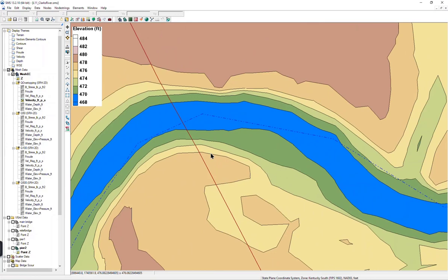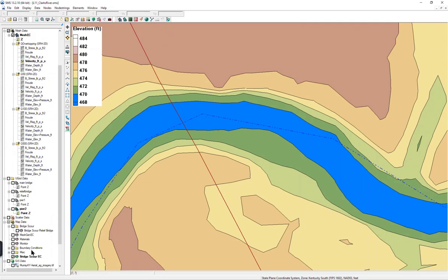As we zoom in on the approach section, we have two options. The recommended option to place bank arcs is at the toe of the slope. And as we see these linear contours defining both banks, there's a fairly distinct toe of slope down here that we will place the first bank arc and the second bank arc.